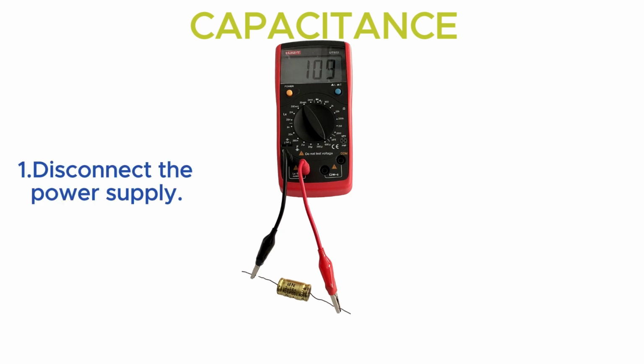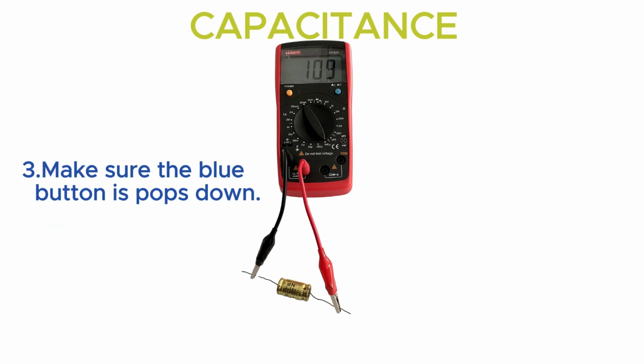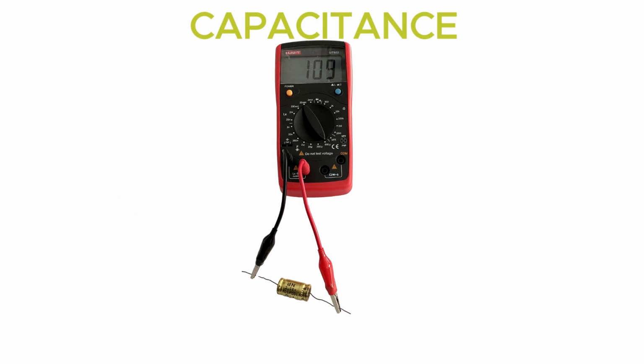Capacitance. 1. Disconnect the power supply. 2. Connect the red probe to the plus slot and the black probe to the dash slot, as shown in Figure 12.2. 3. Make sure the blue button is pushed down. 4. Turn the knob to the F scale. 5. Read the result on the screen.